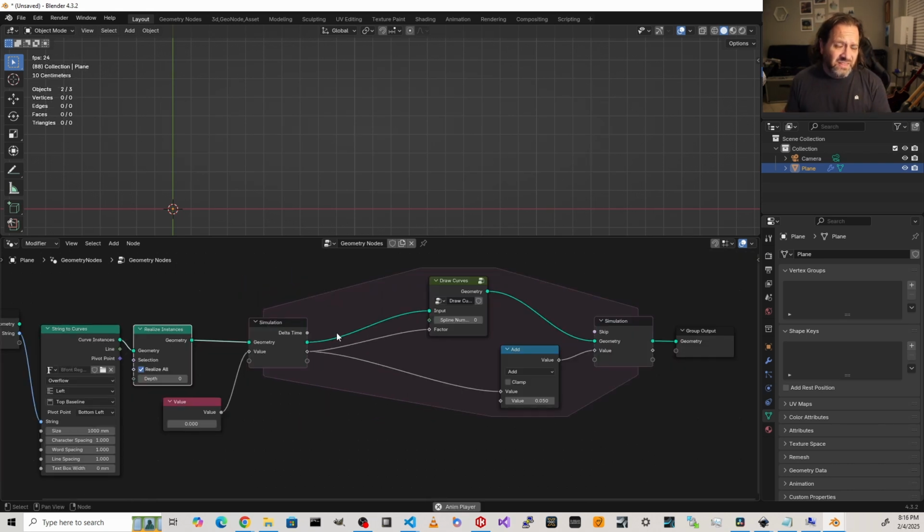As you can see, nothing is happening. And this is a mistake that I made early on. Maybe you haven't made this mistake, but it's one to watch out for. You might think that this looks fine, when in actuality what's happening here is the first time through, we're deleting all of the curves, and the one we're drawing is at 0, and so we basically erased all of the curves. We've sent that to the output, and now we've sent that blank curve object back to the input, and we're trying to evaluate that, and there's nothing there. So the whole thing's gone.